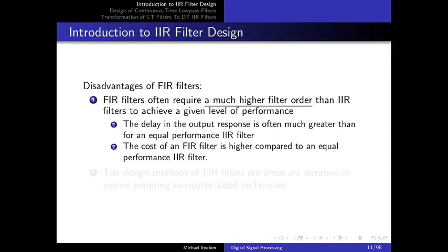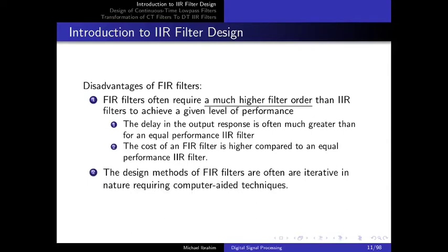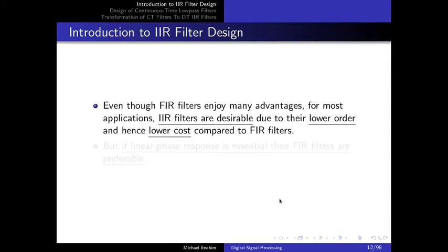And also the design method for FIR filters is kind of iterative. If you remember, we start by designing the filter, checking the specification. If it's not satisfied, we increase the length of the filter, check again. If the specs are not satisfied, we use a different window, and so on. So it needs kind of iteration, and sometimes we can use computer-aided techniques in order to do these iterations.